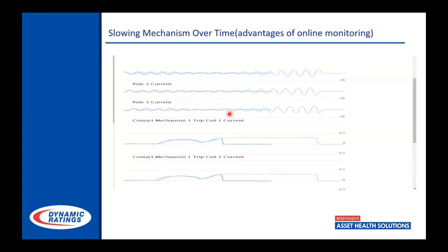And looking at how this current almost goes to zero, and then we see this current, it's about 4 times the normal operating current before it's extinguished. So we're running around, like I said, around 4 amps. We were pulling around 1,200 amps in this portion of the operation.